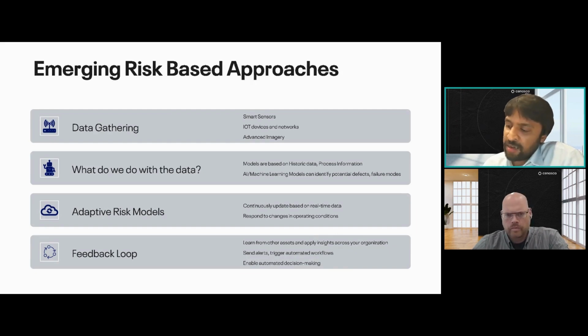So again, this is fairly futuristic, but this is typically where most people, most organizations, industry leaders anticipate that integrity management and RBI approaches will go too. So once you adopt or install a number of continuous monitoring data points, those become your inspection points, inspection locations.